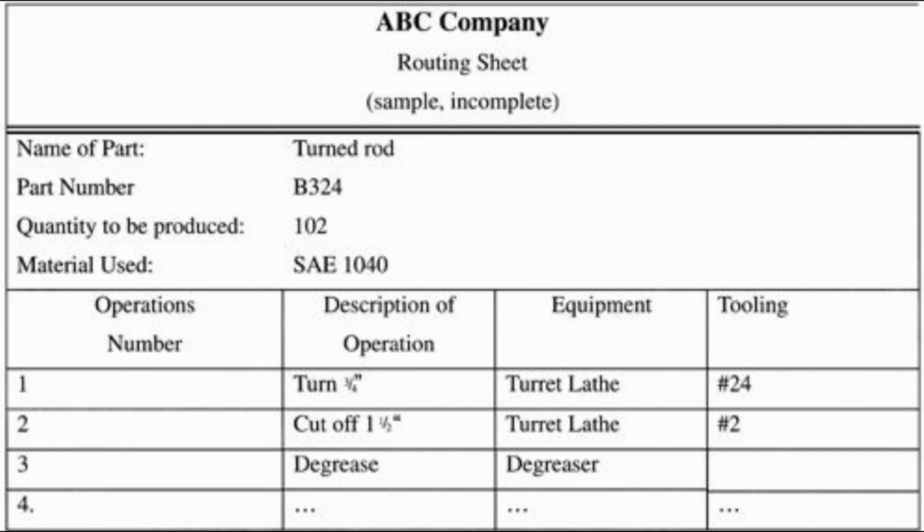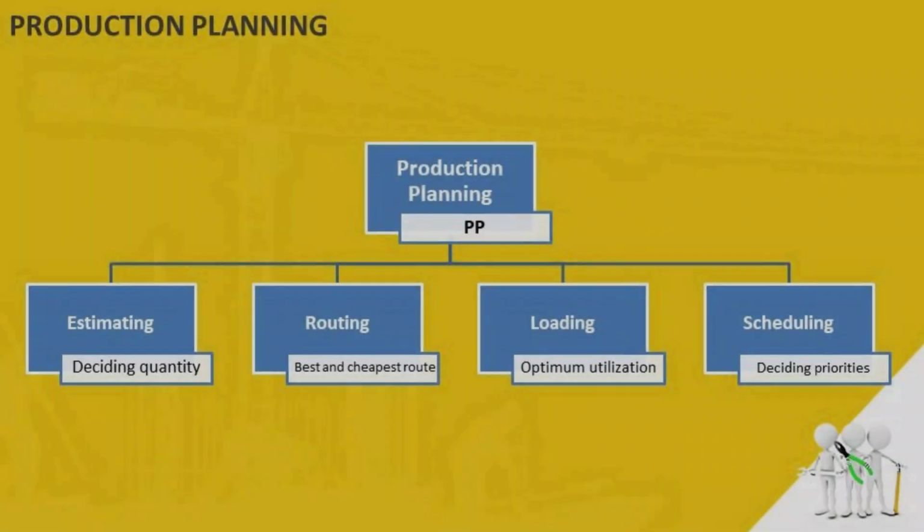A route sheet of a product defines each step of the production operation and lays down the precise route of operations. It includes important details such as product identification number, symbol for identification of parts, number of pieces in each lot, operation data, production rate, and many more. An assembly of a number of component parts, like let's say a printer or a laptop, requires separate route sheets for each of its parts, sub-assemblies, and final assembly. When we understand the product structure, you will get enlightened about this route sheet concept.